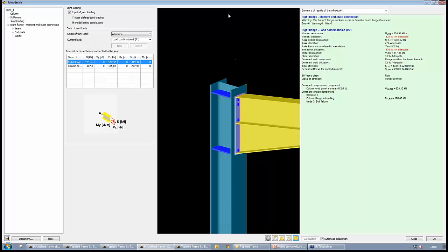So at this point, the bending moment is changing very rapidly. So if we have a very high depth column, then the difference can be very considerable between the theoretical node and this point where we have to calculate the bending moment. And using this frame corner wizard, the identified and placed cross-section automatically receives this bending moment. So this is 319,